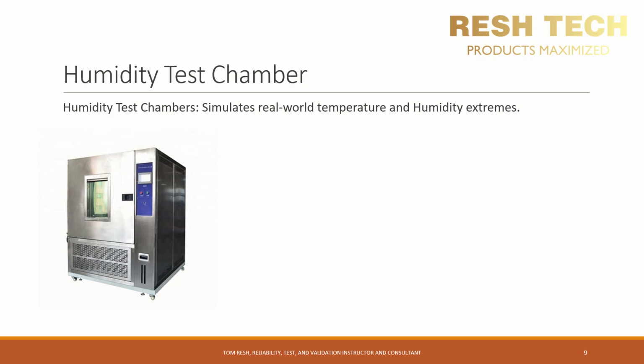As previously discussed, dry humidity environments are produced using a dehumidification coil, or it can be accomplished or complemented by using dry purge to displace and push out moisture inside of the chamber by creating a positive pressure inside of the chamber.